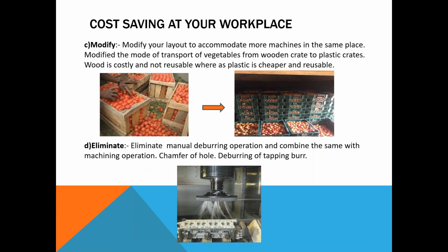Eliminate. I see a lot of things. If I go overseas, I do not see anybody who is doing deburring. Here we spend a lot of money and manpower in deburring or this type of operations. Eliminate manual deburring operation and combine the same with machining operation. Combine like chamfering, deburring, tapping.